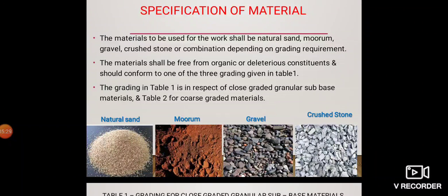Based on performance studies of flexible pavements in several parts of the country like India, it is desirable to select the material of GSB cum drainage layer which fulfills the requirements we have mentioned, that is, the proportion of fines passing 75 micron should not exceed 5%, and the plasticity index should be less.